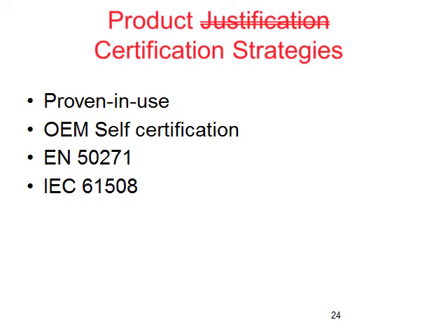We're allowed to use a general piece of equipment and claim a risk reduction up to 10. It's only when we start wanting to claim a risk reduction of 100 or 1,000, these a lot of eggs in one basket scenarios I talk about, that this additional requirement and rigor needs to be put into place. So we want to be into a kind of a formal assessment mode.